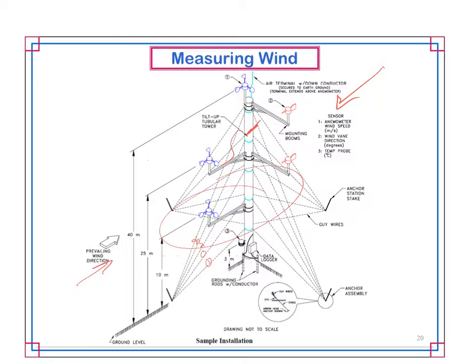You will notice 3 levels of anemometer. Well, if I know the wind speed here, we'll call it V1, V2, V3, and I know the height difference between these two, I can calculate what my Z or my alpha are equal to at a specific location. So let's say that 300-foot tower wasn't tall enough. Maybe I want to get to 400 feet. I can predict what that speed's going to be just by using the coefficients that I calculated from here.